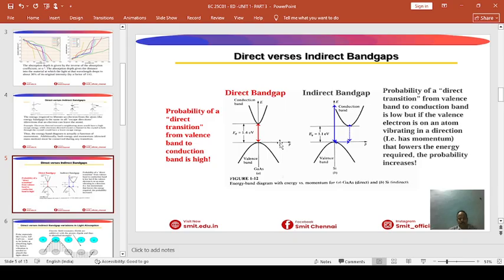This generation rate depends on the absorption coefficient and penetration depth. If the absorption is low, then the carriers are generated deeper in the material. If the absorption is high, the carriers are generated near the surface. This principle is very much used in solar cells, photodiodes, as well as in optical sensors. Photogeneration is a key operating principle for optoelectronic devices.